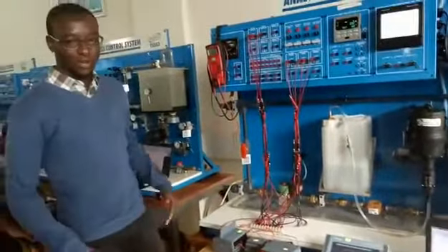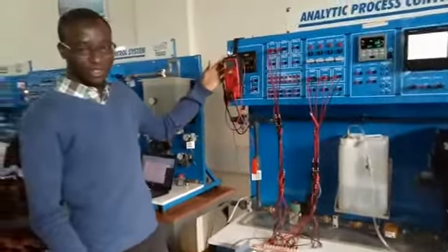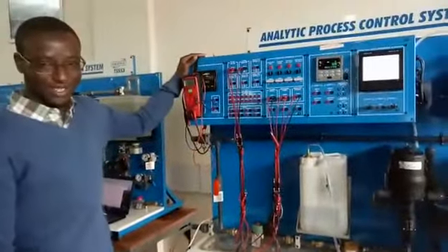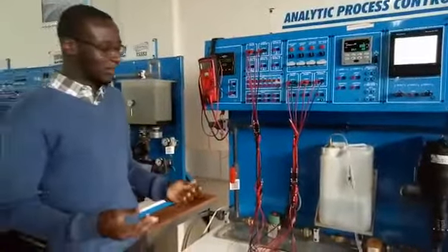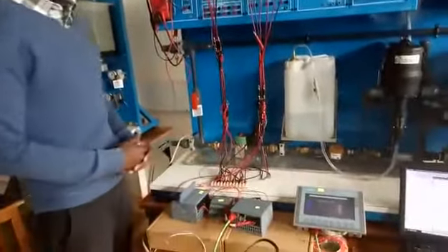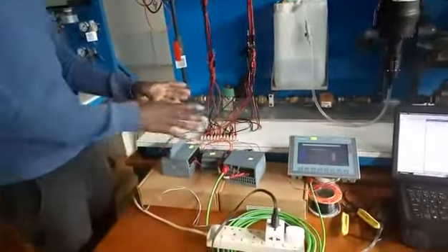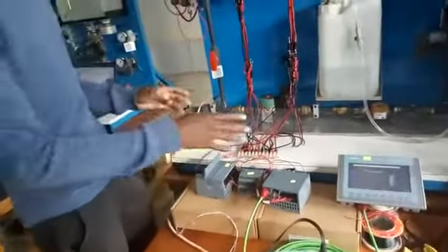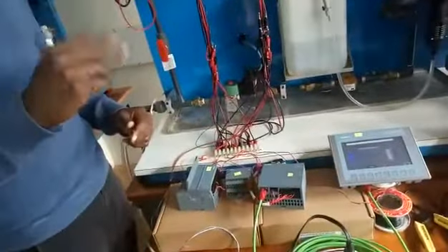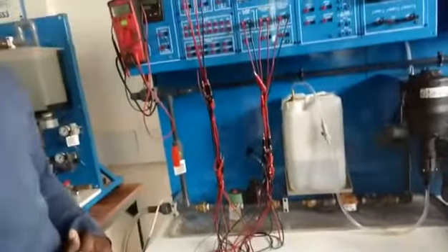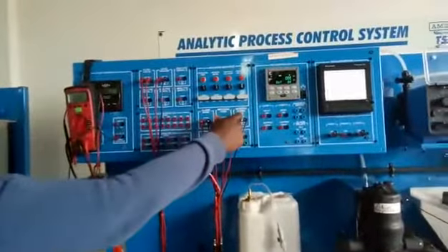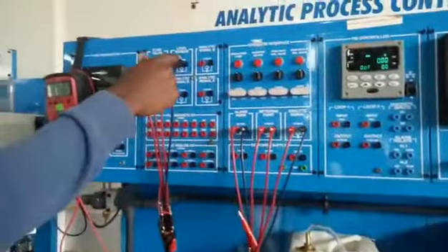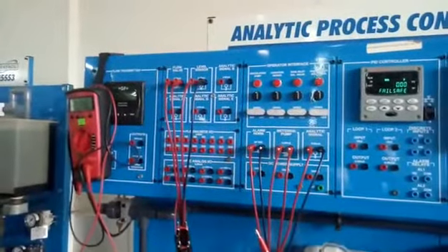Yes, for us to be able to achieve this functionality, we must connect the PLC to the system itself. We did this by connecting some different wires, as you can see. In these connections, we have the PLC controlling 5 main outputs, and the PLC monitoring 2 main inputs. The 2 main inputs that we are monitoring are the analytic pH signal, which we get from the Honeywell pH sensor, and the level sensor, which we get from the pressure sensor.